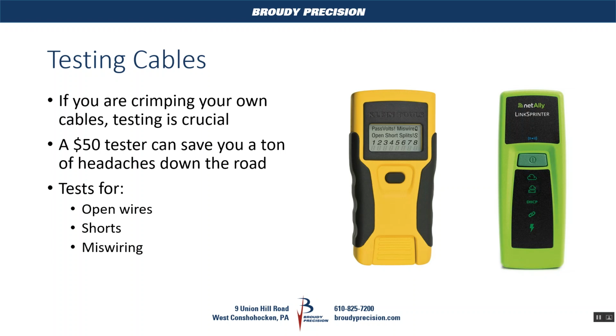So always, when you can, if you're making your own cables, test them. A $50 tester will save you a ton of time. And those testers will test for everything that you would need to know if you're making your own cables. It'll test for open wires, shorts, miswiring if you have pairs or cables on the wrong pair.